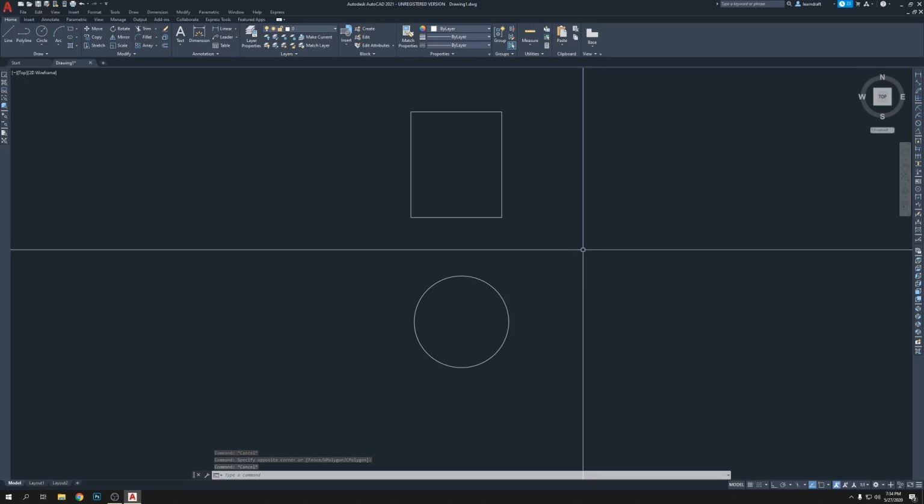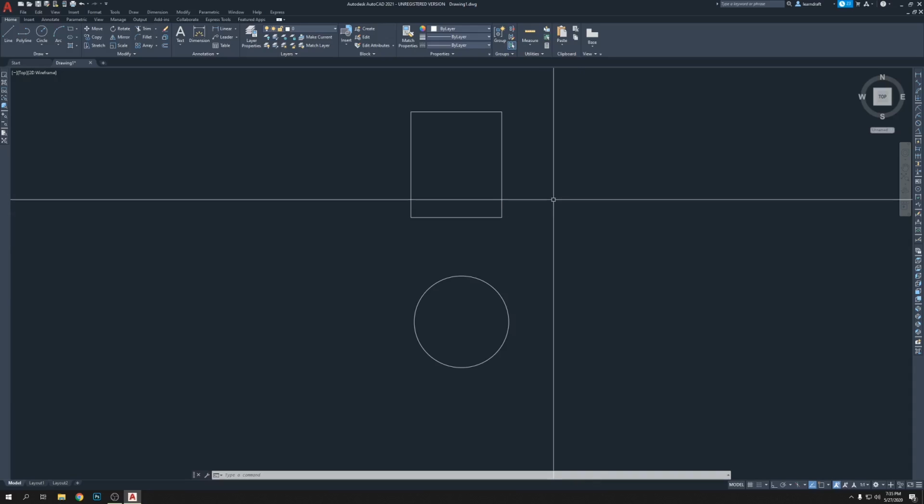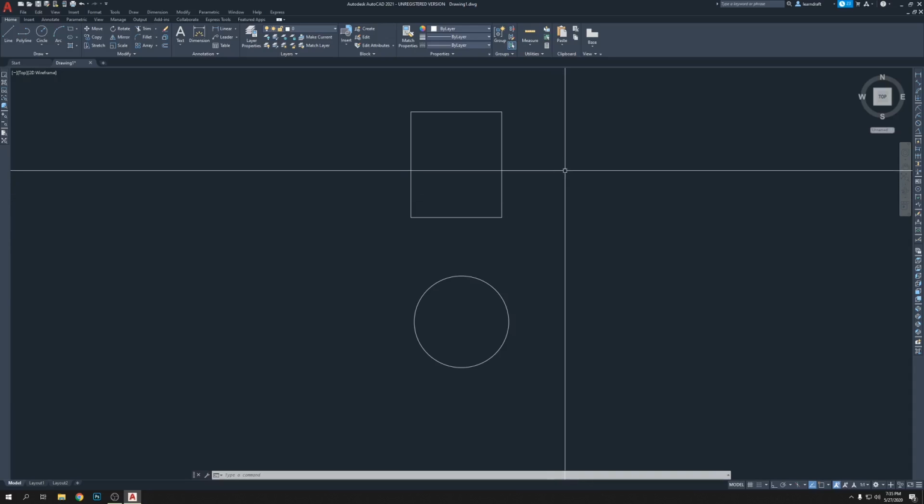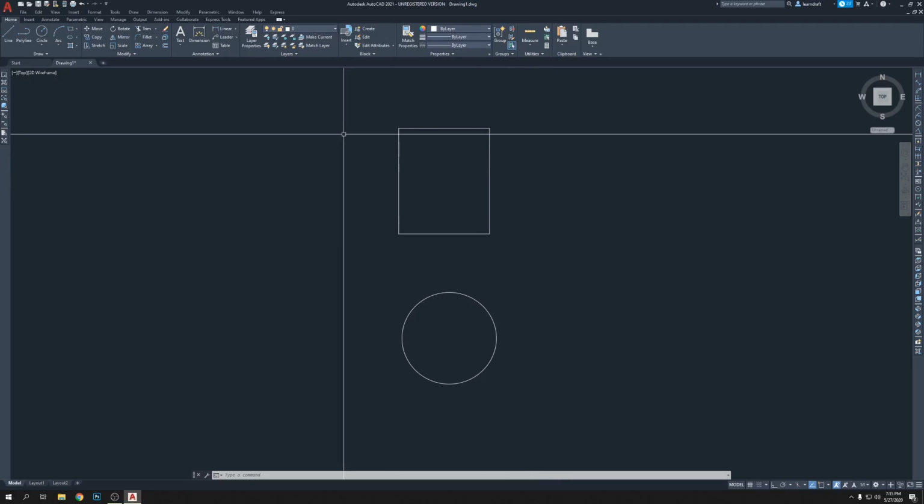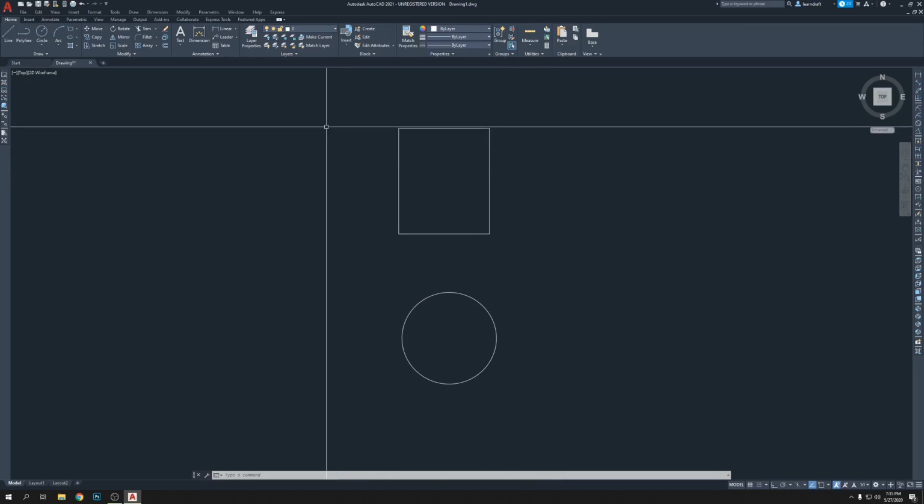Okay, so that's all for number 2: setup unit, text style, dimension style, and views is done. Now save this CAD file. I'm going to keep these 2 drawings, one circle and one rectangle, and I'm going to save it. Why are we going to save it? This is our template in the future, so we do not need to set up anything else. We do not need to set up the format or text style again. It's ready, it's done, it's good.